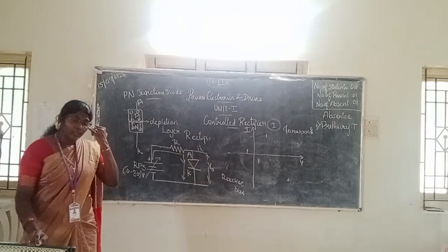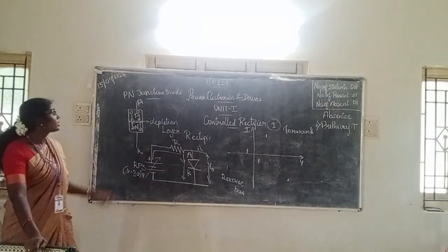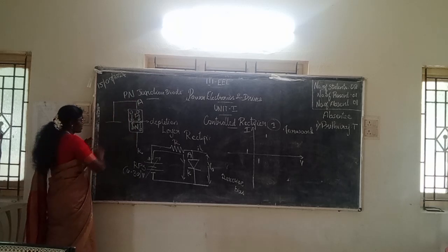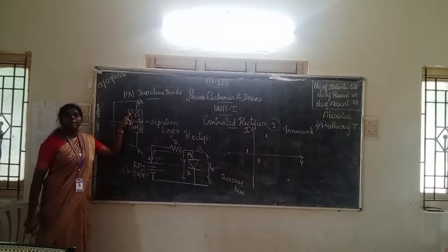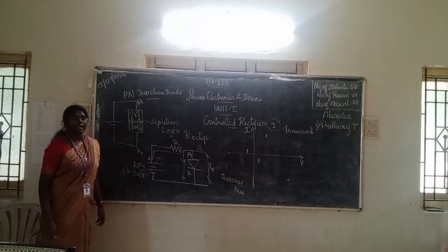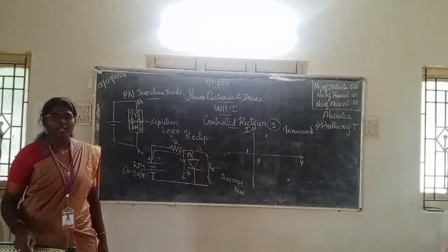When the anode is connected to the positive terminal and the cathode is connected to the negative terminal, the holes from the p-type semiconductor and the electrons from the n-type semiconductor will move towards the depletion region.